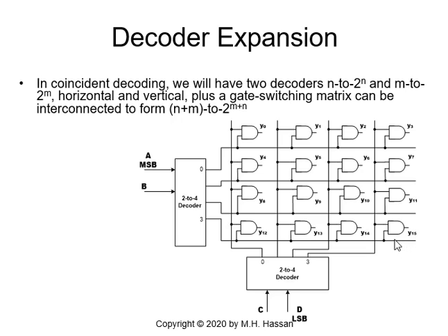So 3 is taken to Y15, Y14, Y13, and Y12. And if I have 1, 1, 3 will be active, which is taken to Y15. So Y15 will have 2 inputs active, the output Y15 will be 1. All other Y's will be zeros.